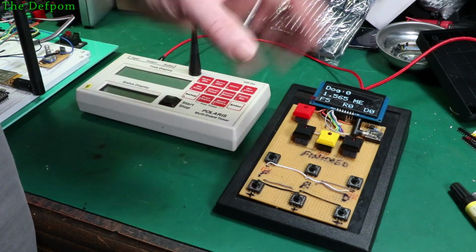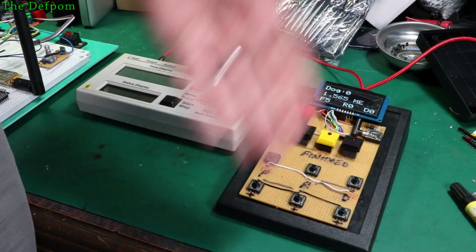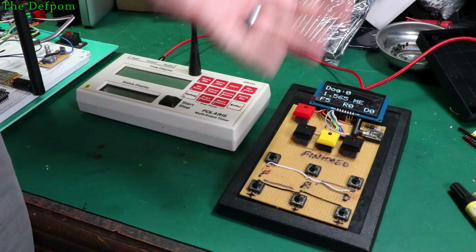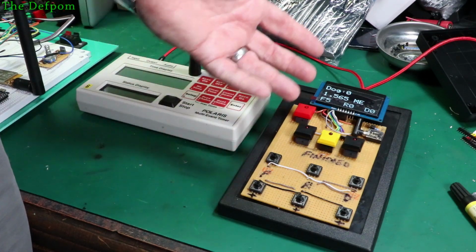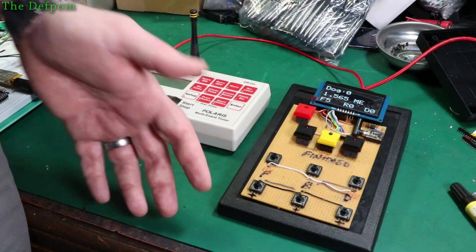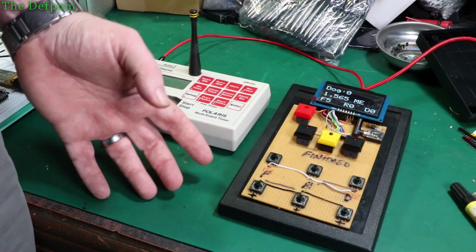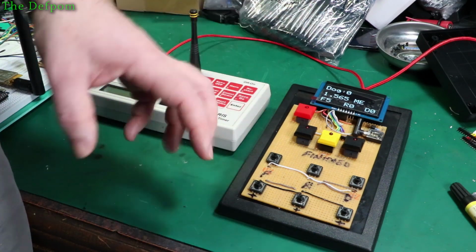Now on top of this particular part of the project, another thing I have to do is an interface for LoRa for the other end of this. Obviously I'm sending data through LoRa. If I've got a Wi-Fi connection, it's fine. It doesn't matter. But I'm expecting to use this at ranges where Wi-Fi won't reach. So that's what the LoRa's for. I need a LoRa interface to receive the LoRa signals and convert that onto my Wi-Fi network and then send it to the website. So it's an intermediate gateway.